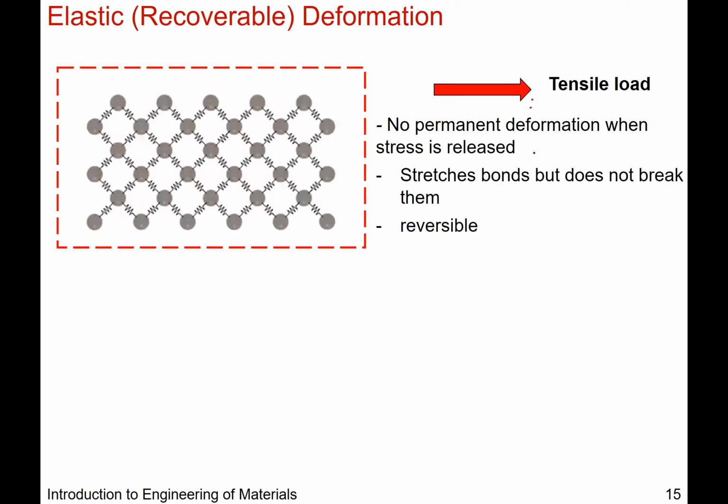Given that this is a material science course, we're going to not only look at the mechanical properties but also where that mechanical property originates from, right? We can go back to that bond energy curve from chapter 2. When we think about the bonds in a system and where atoms are, we've been talking about equilibrium states, right? We've done a lot of work on calculating how there's a preferred interatomic distance where the potential energy is at a minimum, right?